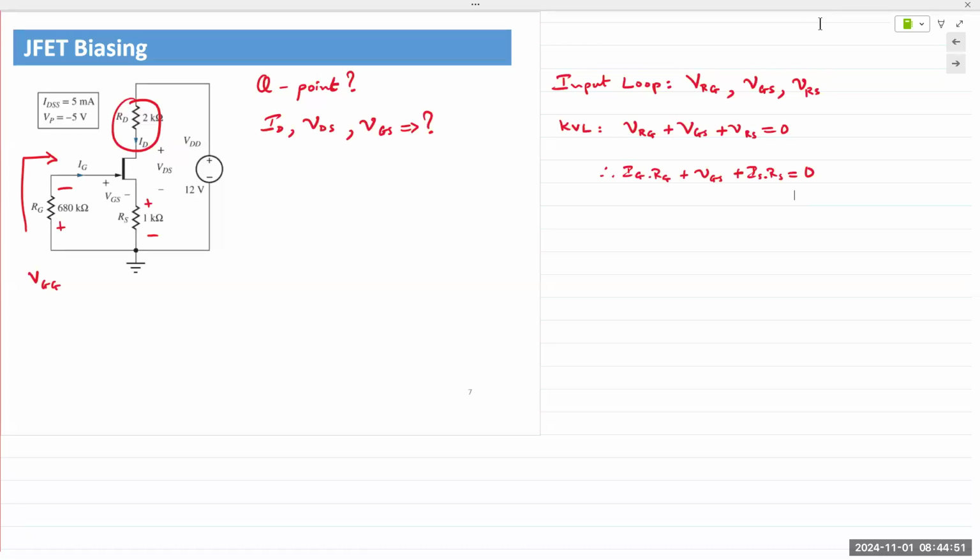Now, here's where it helps with the device physics. The JFET has very high input impedance, so the gate current is almost negligible, almost close to 0. So for many analyses, we can safely assume that IG, the gate current, is equal to 0. And we're going to eliminate variables. So from fundamental principles, we use the IG value as 0.